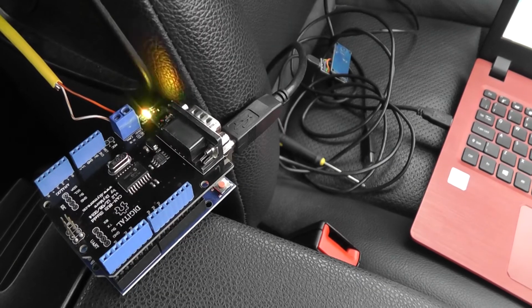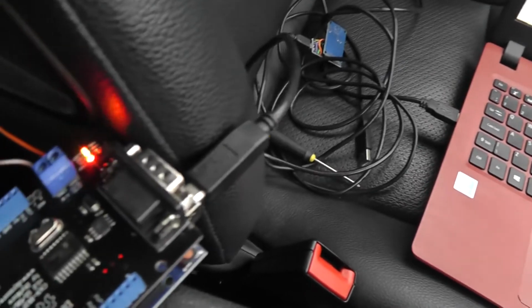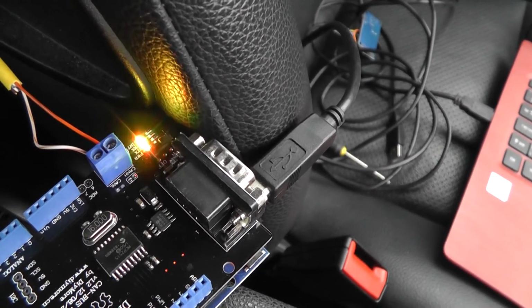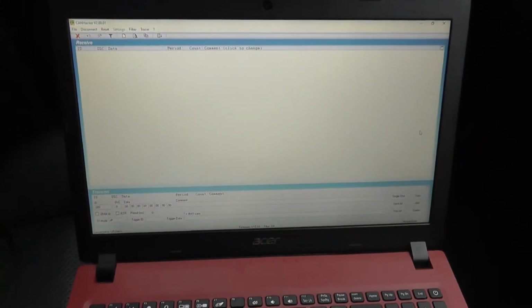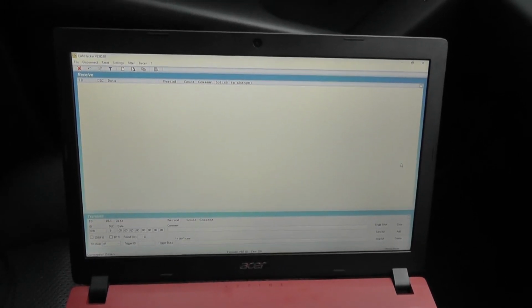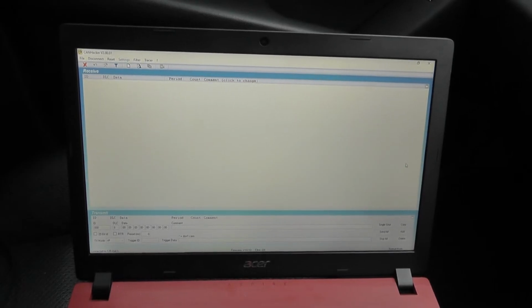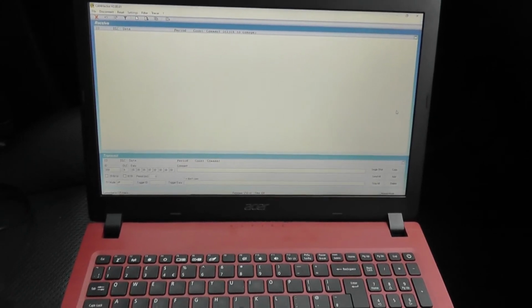Right, well, as you can see, I have reconnected the whole thing into my Arduino Uno, uploaded the sketch, and we're getting zilch on the screen. You can see the CAN lights are flickering, so the shield is receiving CAN, but it's not coming up on the display. I'm not entirely sure why. It may be one of the settings is wrong for this particular shield, or it may be that there's an issue with the compatibility between this software and the Arduino Uno.